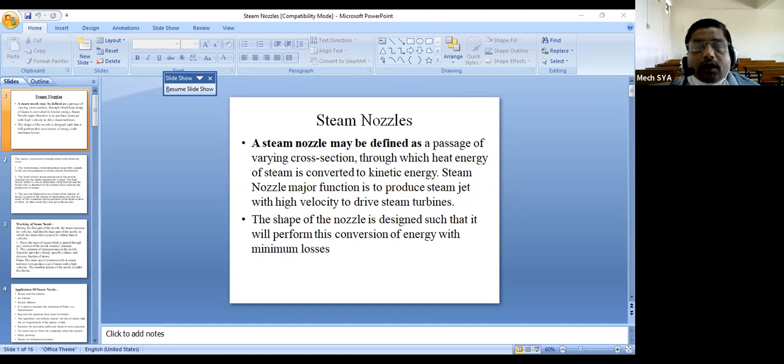Since the mass of the steam which passes through any section of the nozzle remains constant, the mass flow rate of the steam remains constant. There is variation in pressure. The variation of steam pressure in the nozzle depends on the velocity, specific volume, and dryness fraction of steam. Okay, so pressure goes on decreasing, and how much pressure is decreasing?